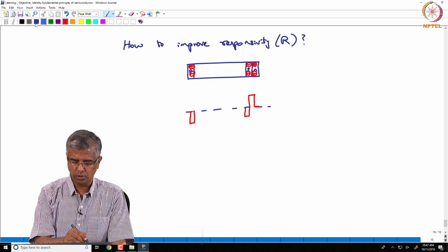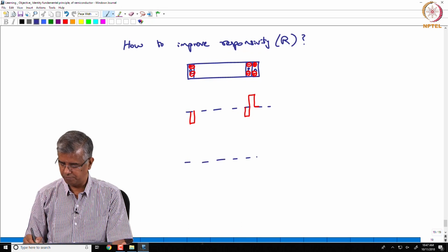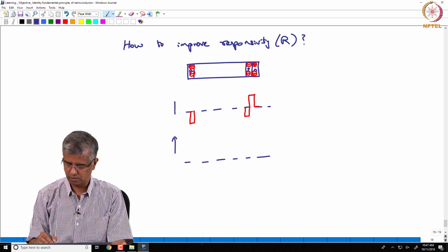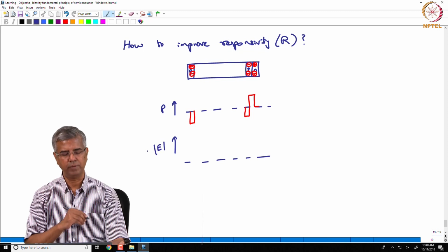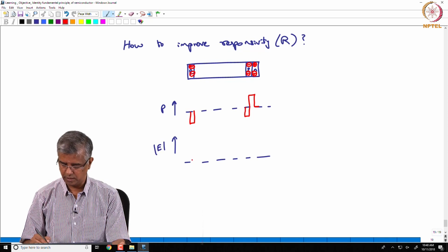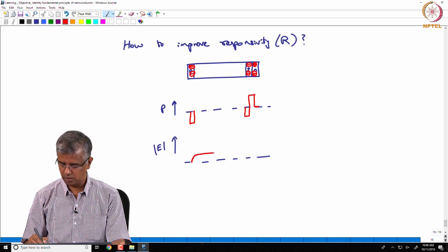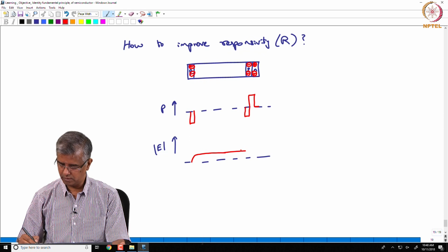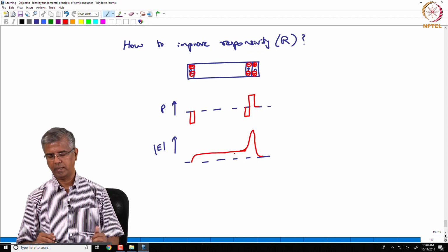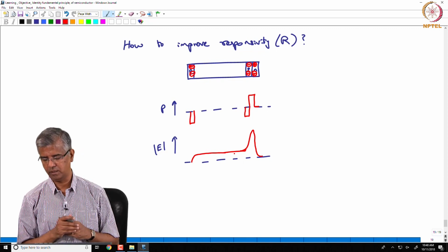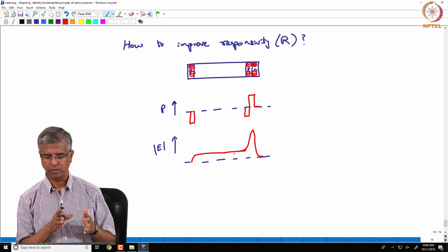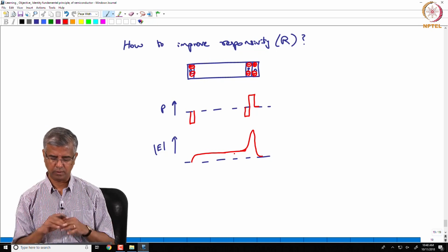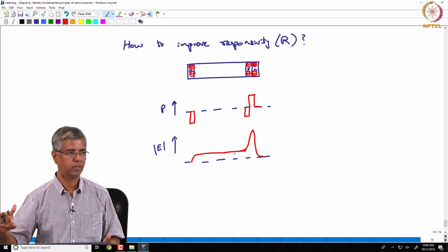So now if you look at the electric field across this structure, so this is basically the charge density rho, but if you are looking at the magnitude of the electric field across the structure, that's going to go like this, and in this region it's suddenly going to spike up because you have negative fixed charges there on the P side, and then as you go, the field is constant, and then there are some more negative charges.